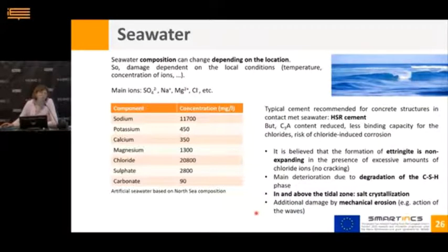So when you look into the literature, what is advised in case of concrete structures that are exposed to seawater, then you see that you should use an HSR cement. That's also what the codes are pointing to. This HSR cement has a lower content of C3A, as we already know. But that means, of course, that there is also less binding capacity for the chlorides, so maybe a higher risk for chloride-induced corrosion. So we should always take care about that.